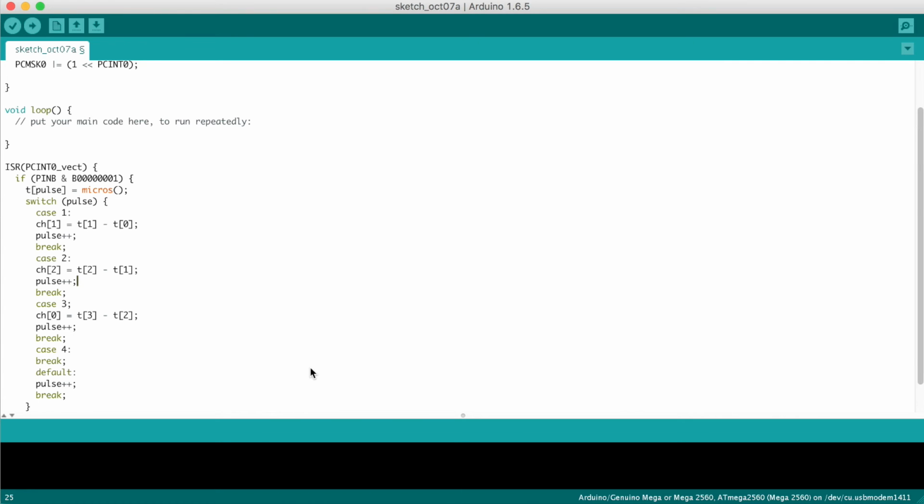In terms of the code, just after we've calculated the channel value, below we're going to write an if condition. And this if condition states that if the channel value is greater than 3000, then we set the timer 0 as the current timer, and we set the pulse value to be equal to 1. So when the next time the program runs, we are measuring pulse 1.